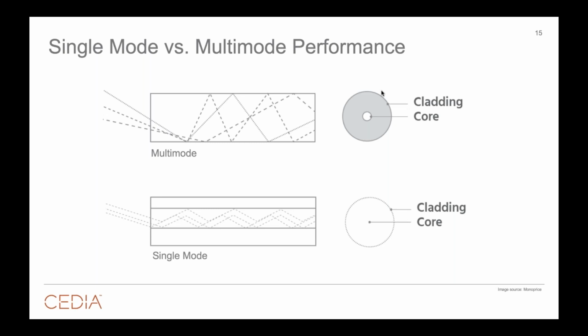Now, does that mean that single mode has to be used only in long distance? No. And frankly, in a lot of commercial applications, you will only see single mode fiber being pulled. Short distances, long distances, demarc wiring, inside network wiring, video wiring, single mode is the predominant cable. Multi-mode is what we see in a lot of residential applications. You see it in a lot of shorter distance networking applications. There isn't necessarily a right or wrong choice when you're going longer distances or shorter distances, I should say.